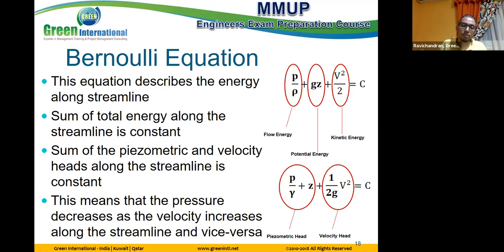Back to the last session, you remember I told you we can describe pressure in pressure form or head form, correct? Same like pumps. Because the pressure is equal to gamma H, I can describe the pressure of the flow directly, or by H, the head, which refers to the pressure effect. Here also, we can write the equation in the energy form, the head form, or the pressure form.